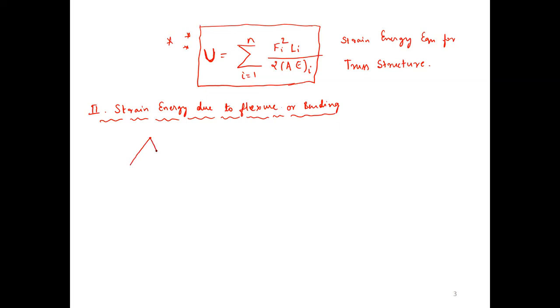See, in a beam, what do we do? We take one small elemental part for the curvature, that is, the beam is bent in deformation. Flexure means... so this is the point O, and it is subtending this as theta, and this is radius R, and this is L, that is length. For this type of bending, there may be a moment M applied. Now what is theta? If you neglect curvature, consider it as a triangle. What is the theta value? Opposite by adjacent. L by R.